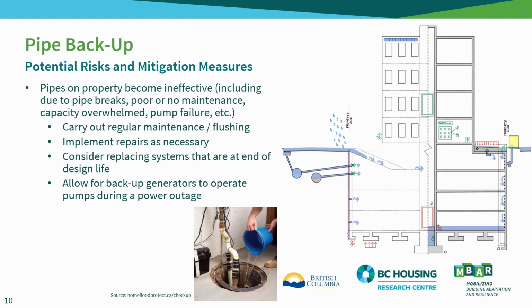life. If your building has pumps, ensure that there are backup generators available to keep these pumps in operation during a power outage. The fuel for these backup generators should be renewed at least annually to ensure it can be relied upon when needed.